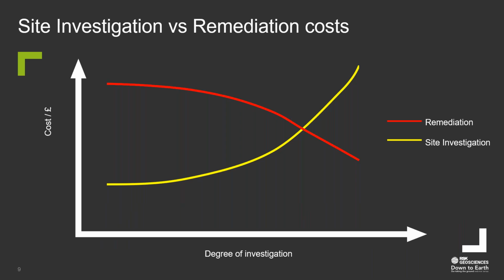Insufficient site investigation increases unknowns and uncertainties, leading to higher remediation cost. Think of in situ groundwater remediation like a blank canvas. If we can't see anything, with only a few data points, we are trying to model the site to find the solutions. So it's like building Lego. We can't have a finished product with a couple of pieces. So we need to continue the site investigation until we have enough data to develop a robust CSM, conceptual site model. Only at this point can we design an appropriate, effective, economical, and sustainable remediation approach for the site.